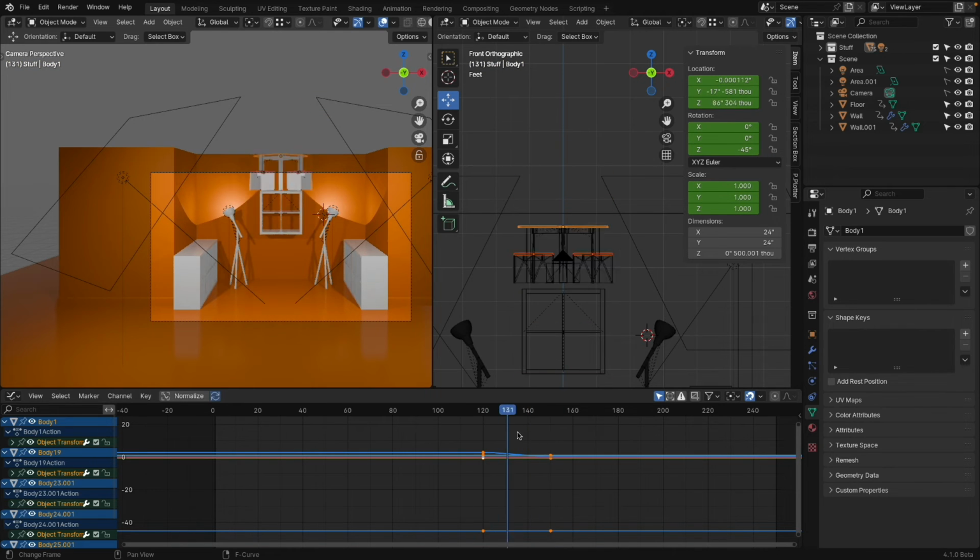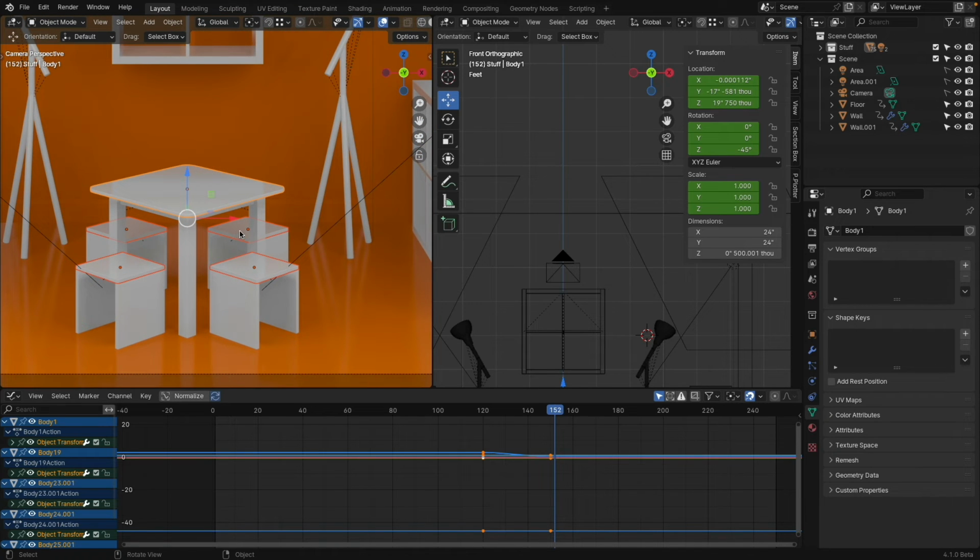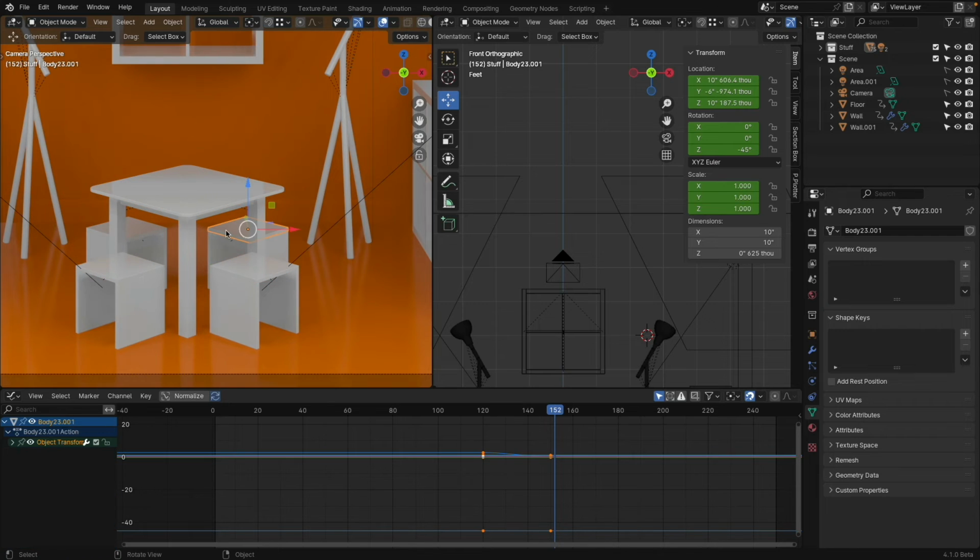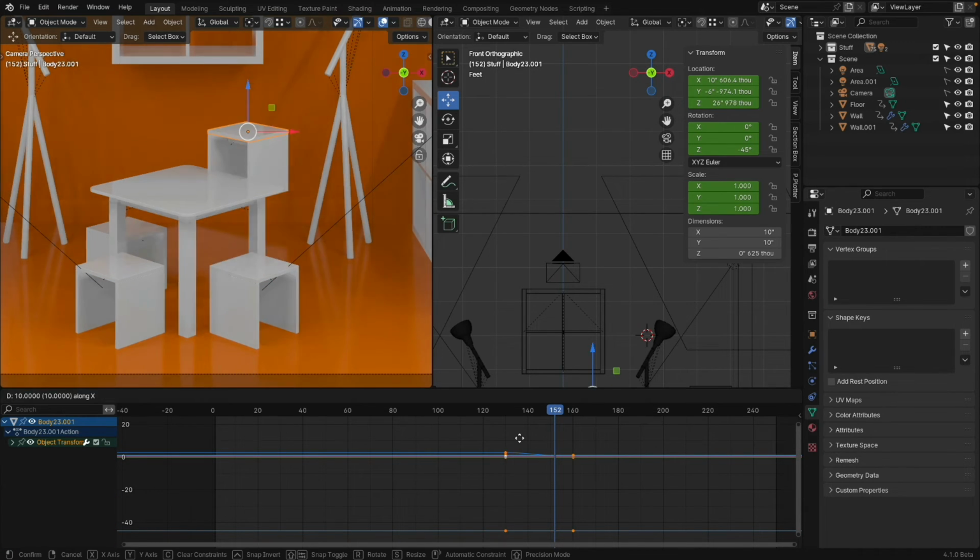And this comes down. I would, however, like to have them kind of like one by one come down. Because I actually created all the keyframes already, I can do the following now. They all get 30 frames. This is my second object. I select everything, press G and X, and move this 5 frames.